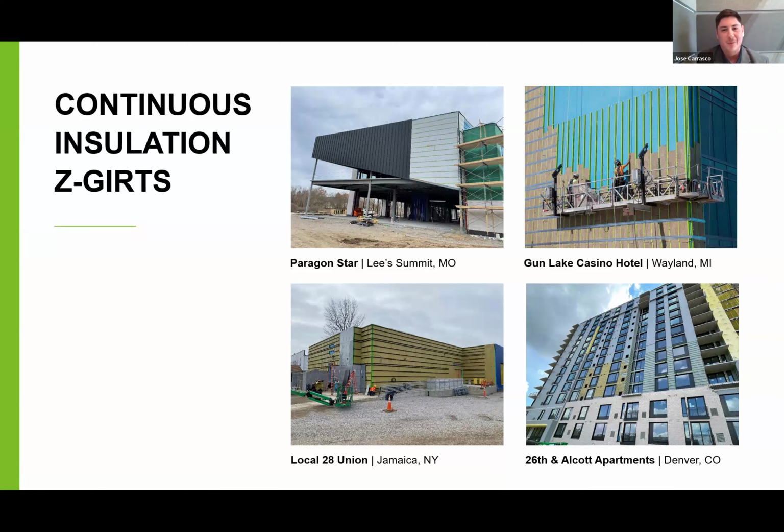So Z-girts are compatible with mineral wool, spray foam, rigid board insulation of any kind, as well as compatibility with various types of cladding. So that bottom right image there, you can see there's several different types of cladding that are being used and incorporated with those Z-girts there.